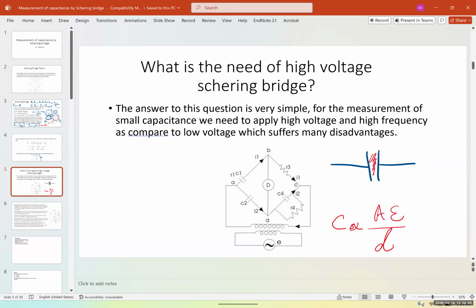Obviously, if you have a capacitor, you cannot change the area. You can't change the insulation. The only thing that you can change is what? The distance. Now, the problem is these distances are around 1 millimeter or something less than that. So a very small adjustment is going to have a huge effect. It's very difficult. Even an impact could change the capacitance. That's the reason these capacitors are expensive and very difficult and not very accurate.